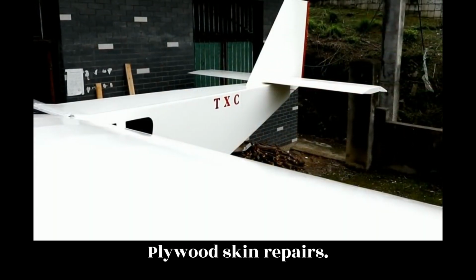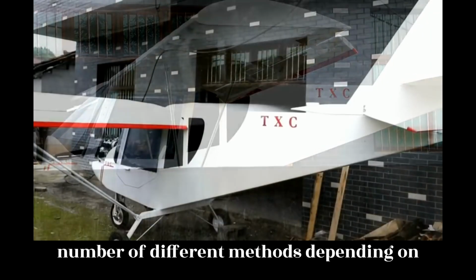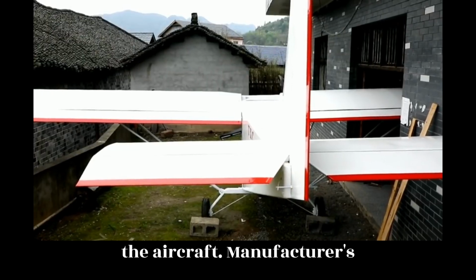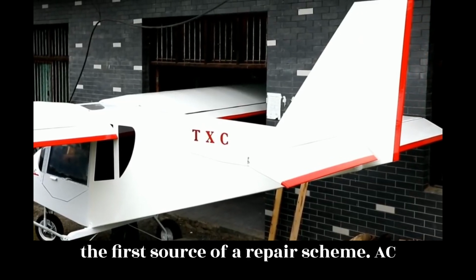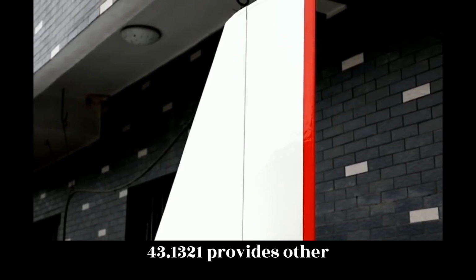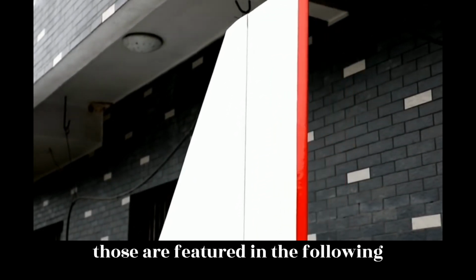Plywood skin repairs. Plywood skin can be repaired using a number of different methods depending on the size of the hole and its location on the aircraft. Manufacturer's instructions, when available, should be the first source of a repair scheme. AC 43.13-1 provides other acceptable methods of repair. Some of those are featured in the following section.